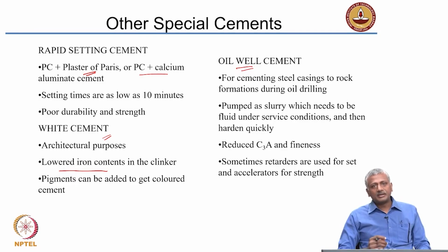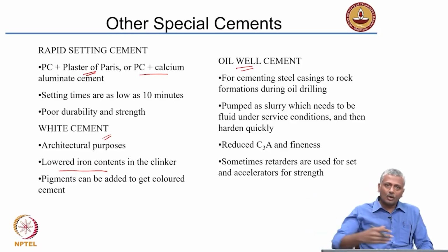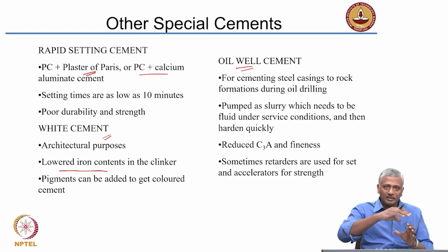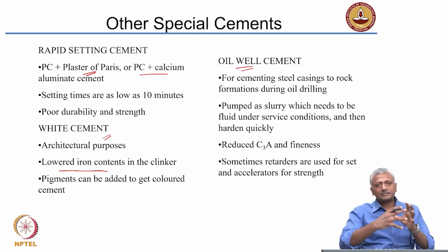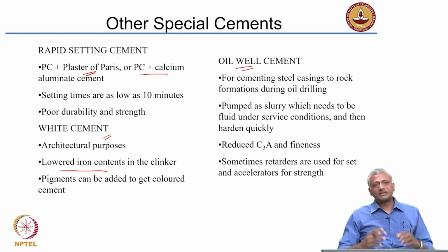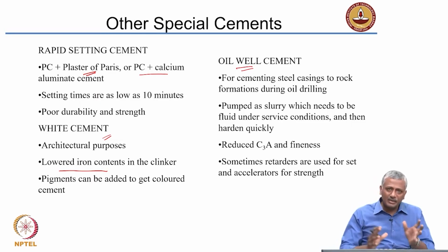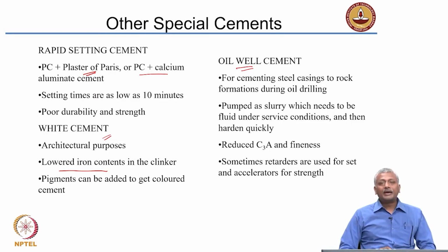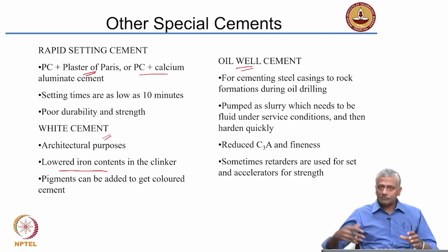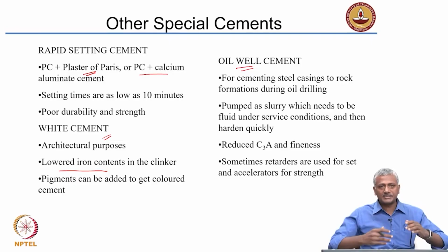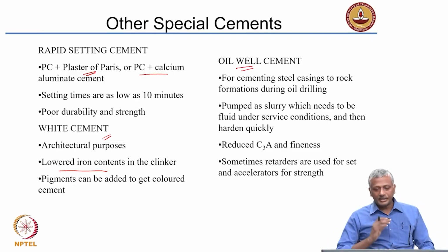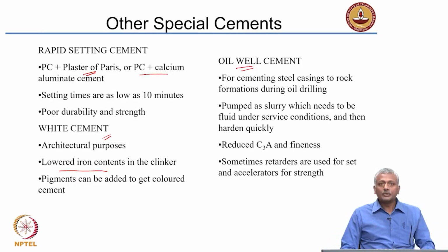And the cement should be such that it can flow very long distances after mixing, but at the same time when it comes to rest, it should form a layer on the soil surface so that the soil does not cave in. So, it is a very uniquely formulated cement, and it needs to have a combination of different types of additives to ensure that it is flowable for a long time, but when it comes to rest, it sets and hardens almost immediately. So, again this is something that needs to be formulated very carefully.